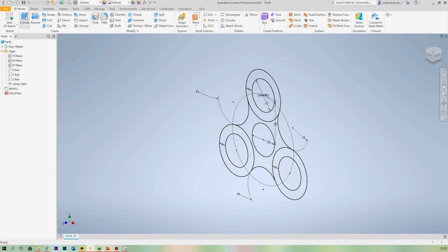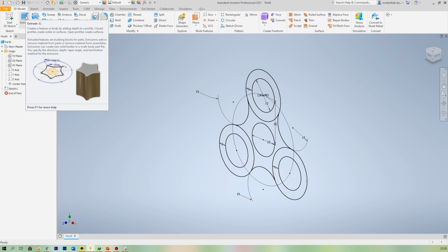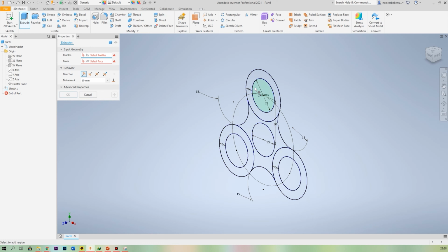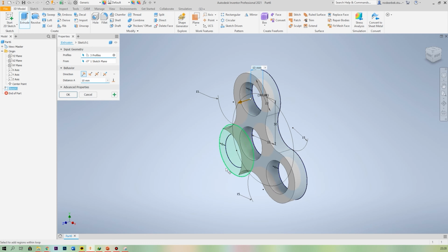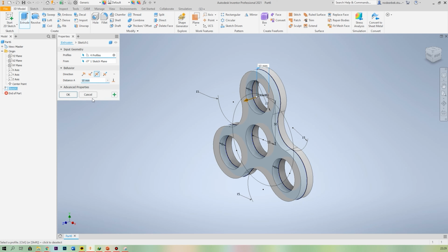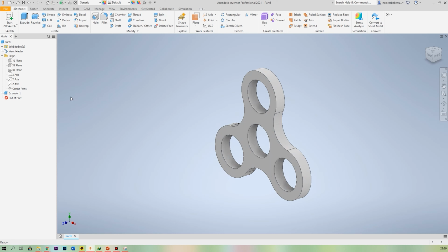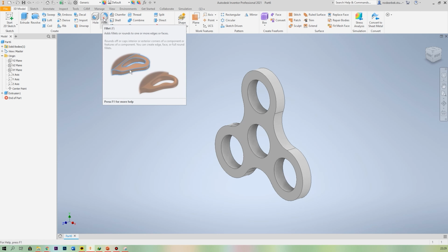Click the wheel of your mouse 2 times to put your sketch in full size in your workspace. So now we need to extrude it. Let's choose extrude, and first of all select the areas which should be extruded. I already selected. Then from here choose the symmetric option, and the distance should be 7 millimeters. Done.